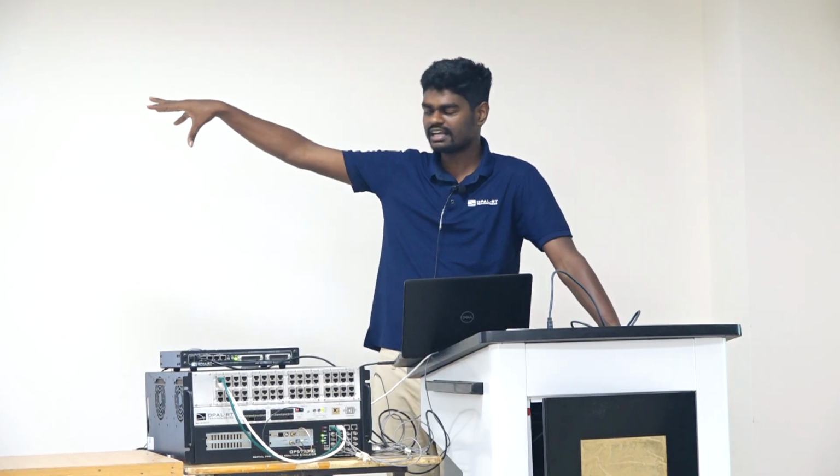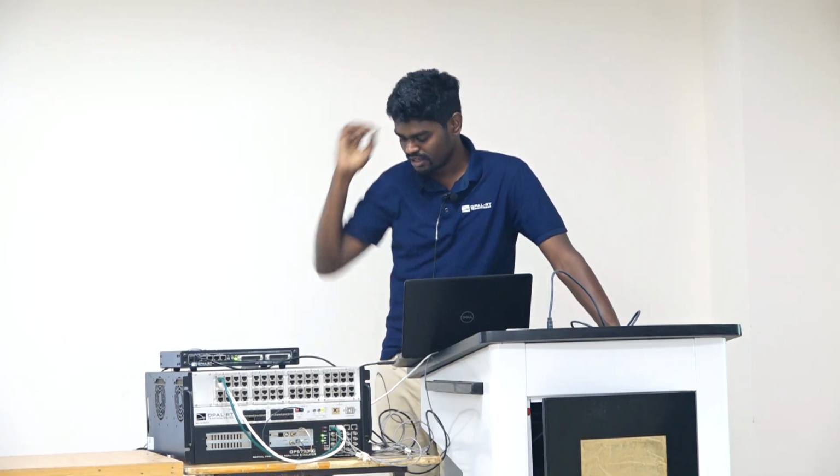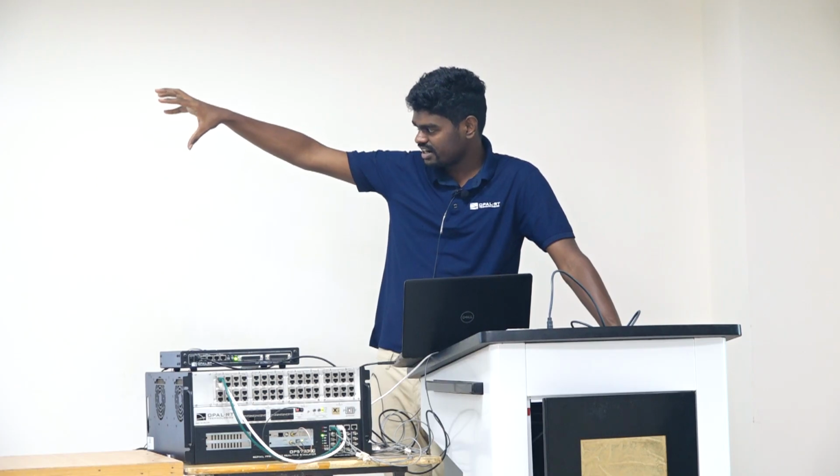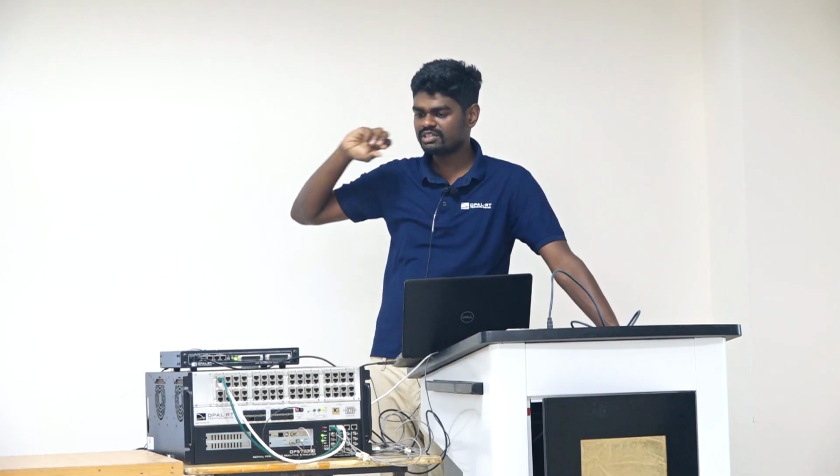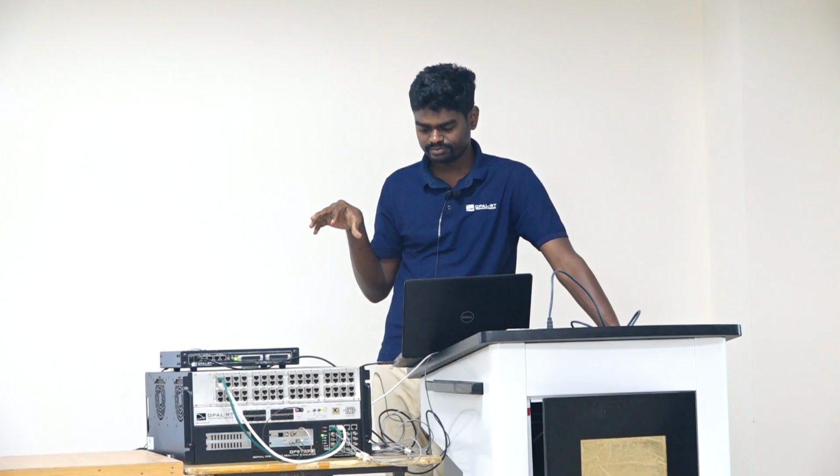To put it briefly, the top level of your simulation should have only subsystems like what I have here. One subsystem is called the master, and the other is the console. Master is a subsystem which will have your plant, whatever is going to be computed inside the CPU. Console is something which will help you interact with the simulation while you are running it. The console will have all the scopes and some control variables. If you want to change any parameters in the simulation, all those steps will be in the console.